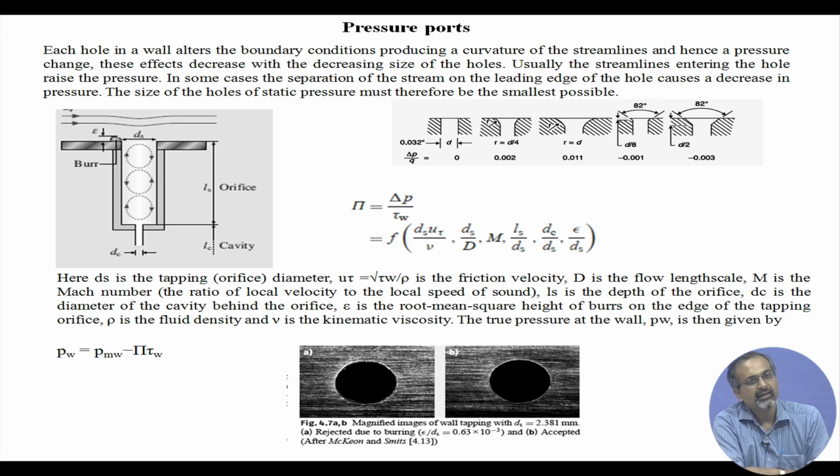And mind you, on a practical model you may actually have hundreds of these pressure ports. If it is a large model which you are testing in a bigger tunnel, the pressure ports are not necessarily few in number, very often they are enormous in number, and you have to take extreme care that each of them is made well.